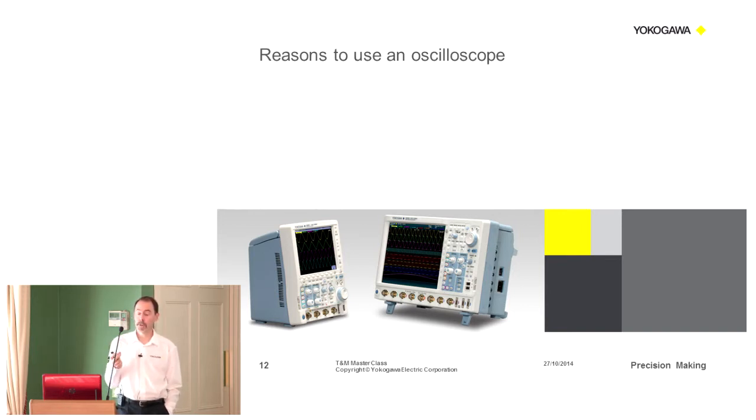But of course, modern devices and modern technologies, LED lighting or other high frequency usage, mean that there are elements of higher frequencies, and that's why you've got power meters which are specified at 1 meg, for instance, or even 2 megs. There are issues with that to do with how you prove or how you can show that your instrument is actually accurate at those frequencies, because there are no international standards which offer you a guarantee of calibration at 1 megahertz. Essentially 100 kilohertz is the maximum you can get.